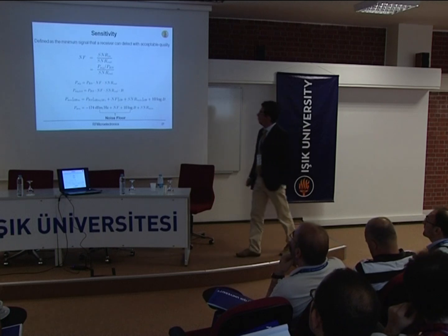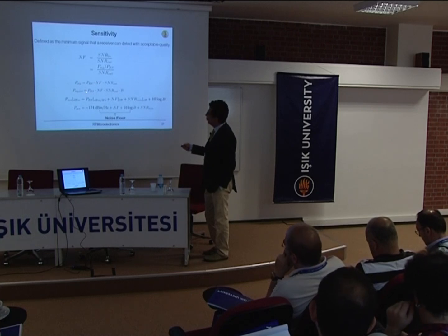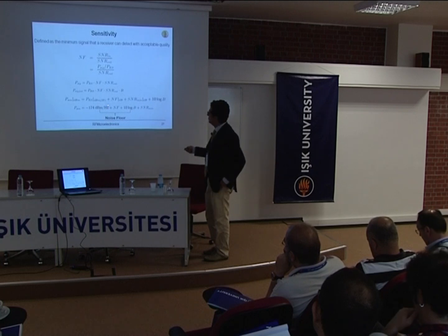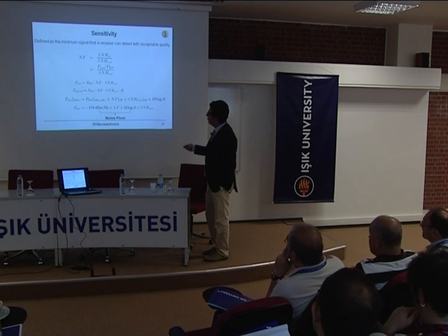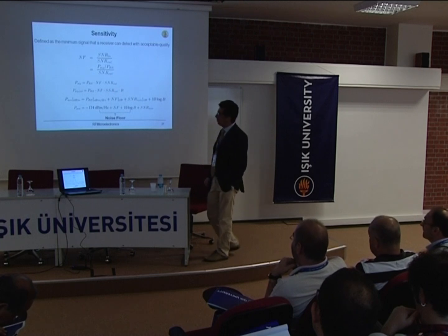Okay? Now, of course, this is a power spectral density. So this will also be a density. So to go to a power in dBm, to the actual integrated power, we just multiply the second term by B, the bandwidth, and we'll have the total power at the input is related to the noise power density, times the bandwidth, times the noise figure, times the signal to noise ratio at the output.